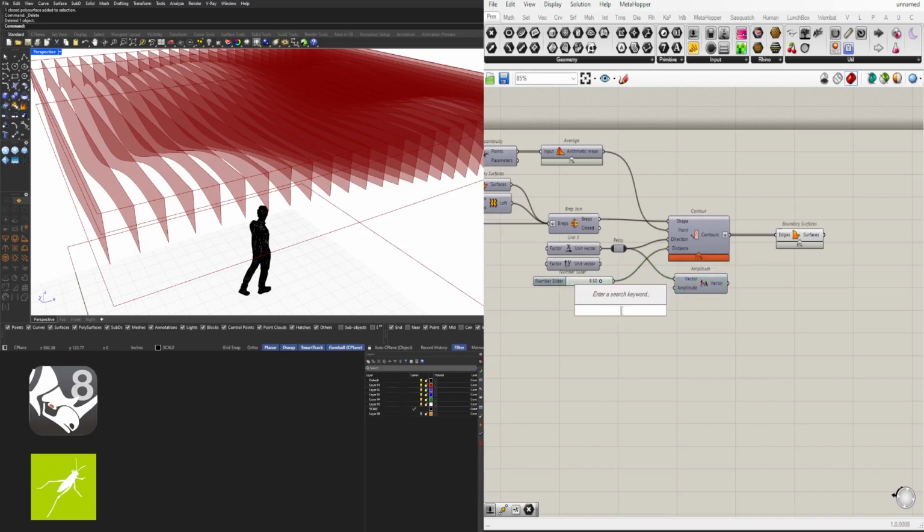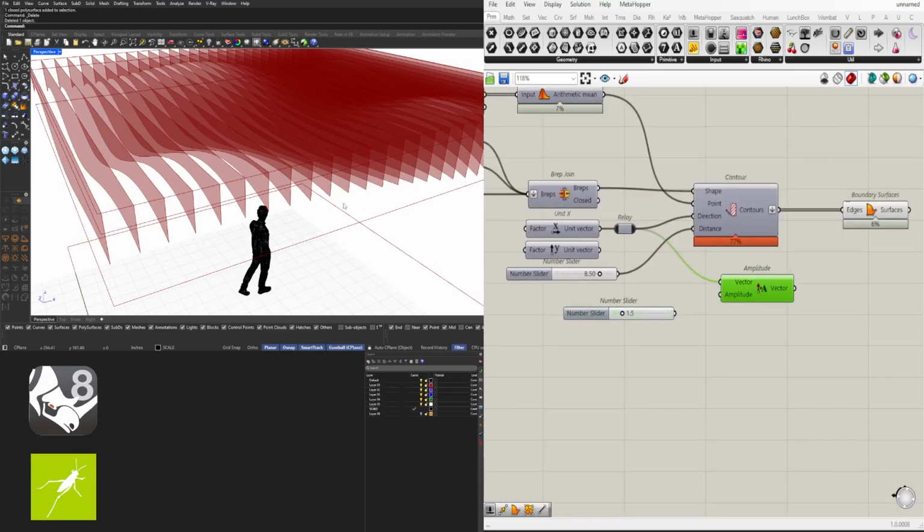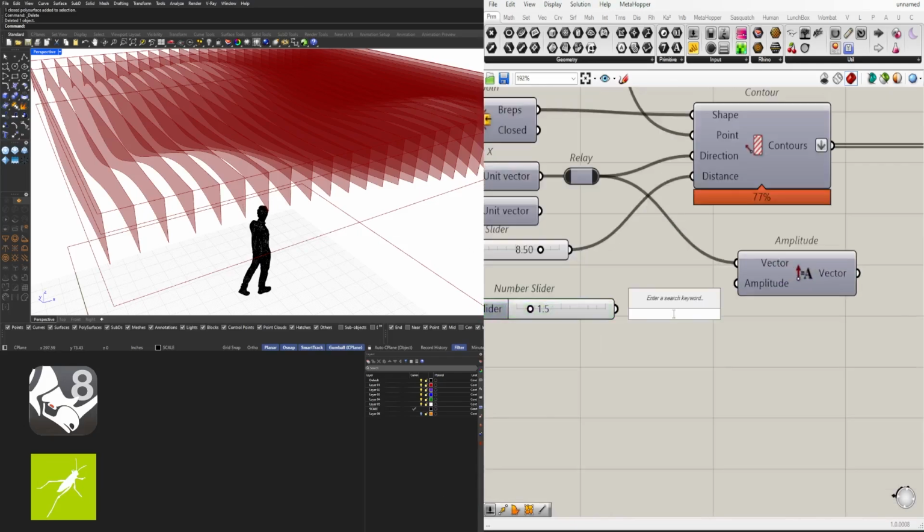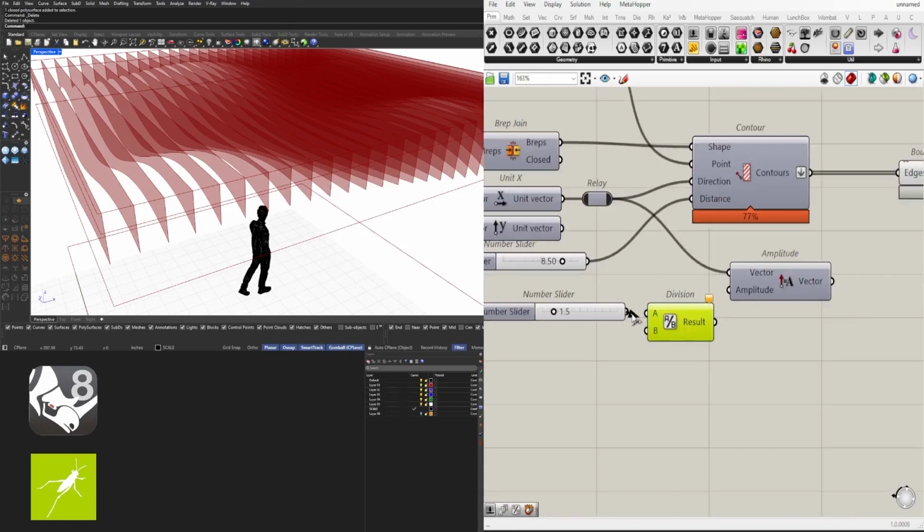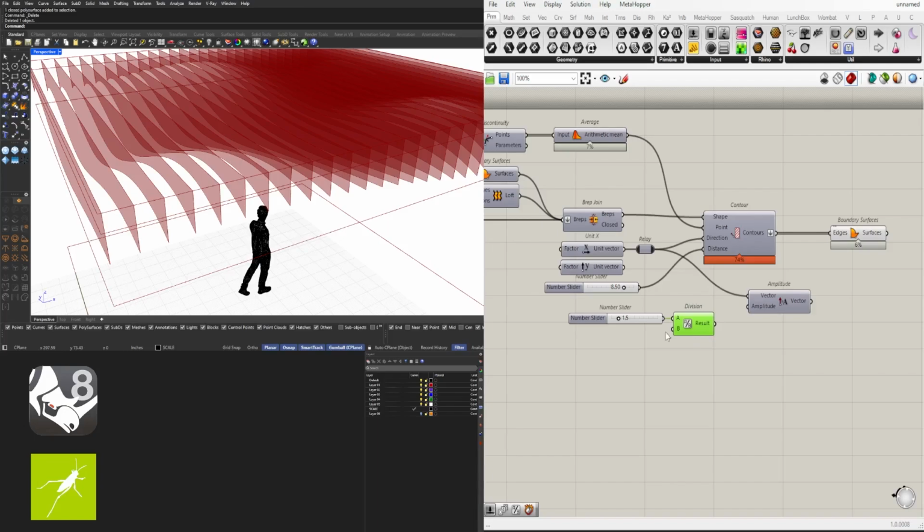Then the thickness or the depth of each contour will just go to 1.5. But since this is the midpoint, we actually need to do 1.5 divided by 2. And you'll see why this is critical. So we'll just make it 2 here, to kind of show you the idea. Divided by 2 is going to be 1. And so we'll move it by 1 in the X direction.